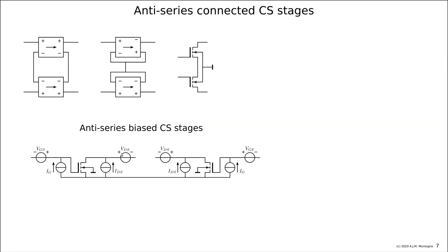You could say we have a plus input and a minus input, and now we also have a plus output and a minus output, and by flipping them we can make either an inverting stage or a non-inverting stage. So that's the degree of freedom that we get from the differential pair. So we have a 4-terminal stage with improved port isolation. That can be very useful for us later on in the design of amplifiers.